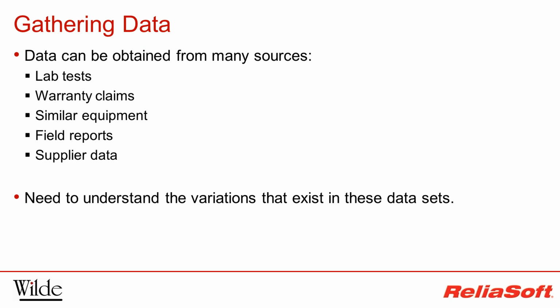Warranty data, on the other hand, can be difficult to interpret, as we need to confirm how many hours have been accumulated and the mode of failure. It is usually necessary to get failed parts back for review and confirmation of the root cause. However, warranty data provides us with real use conditions and so may be a far better reflection of the failure rates that will be experienced than improperly designed in-house tests. Ultimately, it is better to have half a dozen trusted data points from a clearly defined failure mode than hundreds of subjective selections.